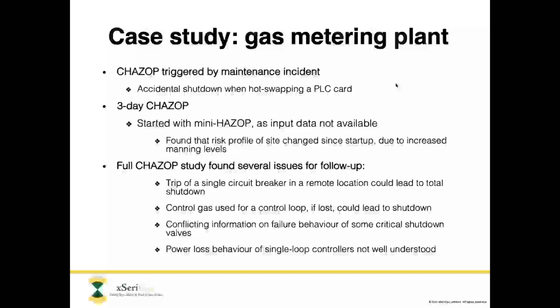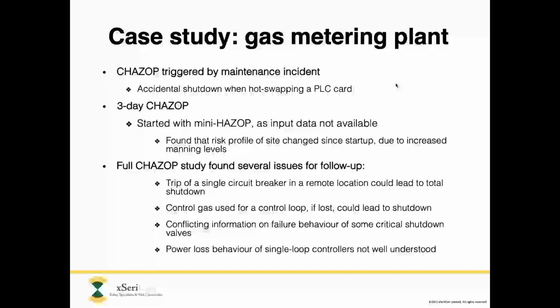And to me, that was really the, can we say, the value of this whole CHAZOP study. It paid for the CHAZOP study many times over, just finding that one result, because clearly that was the major potential source of loss of availability for their plant. So that was the main recommendation coming out of this study, to address that and to try to deal with the lack of redundancy in that particular power supply.